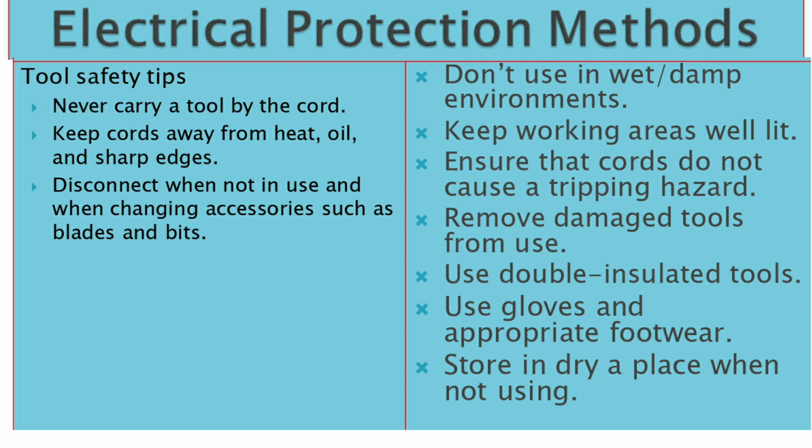Tool safety tips. Never carry a tool by the cord. Keep cords away from heat, oil, and sharp edges. Disconnect when not in use, and when changing accessories such as blades and bits. Don't use in wet and damp environments. Keep working areas well lit.